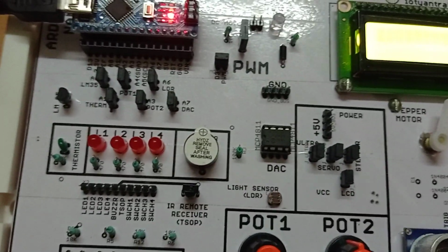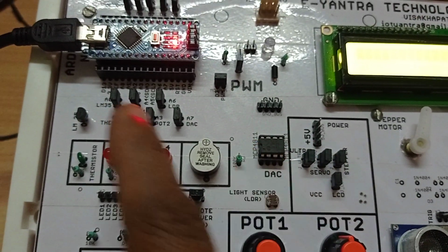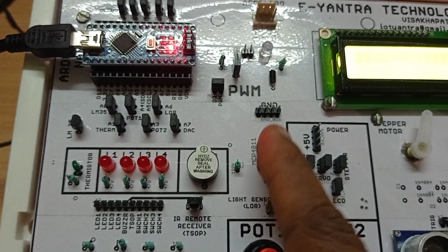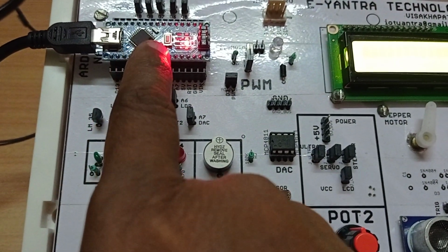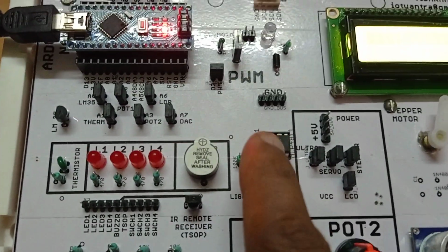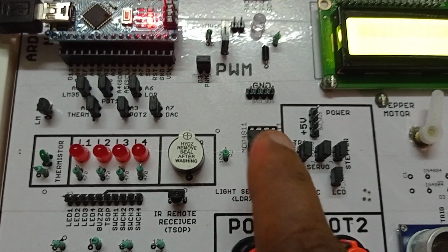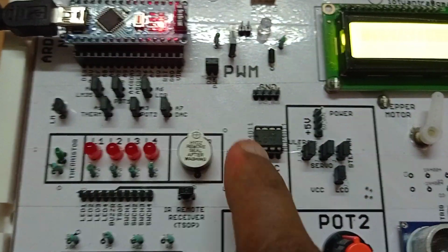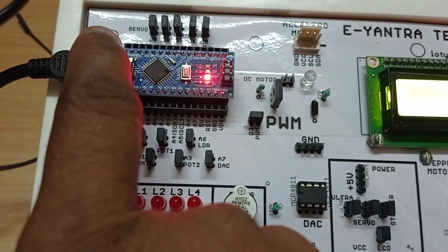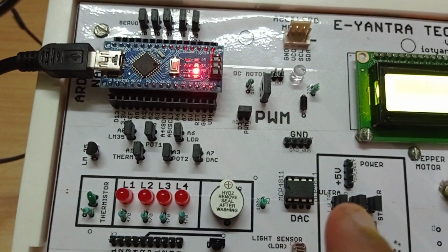General SPI protocol requires 4 wires to be connected, but here only 3 are used. The reason is, the Arduino is the master and the DAC is the slave, and the slave is not sending anything to the Arduino. The master is just sending commands and is not listening, because the DAC's purpose is only to read a number and accordingly set the output voltage. It has nothing to send back. That's why the 12th pin on the Arduino, which is MISO, master in slave out, is not used here. Otherwise, for general SPI protocol, you need to use all 4 pins.